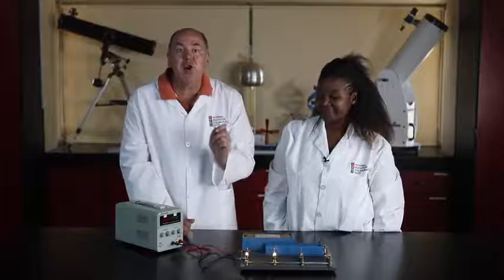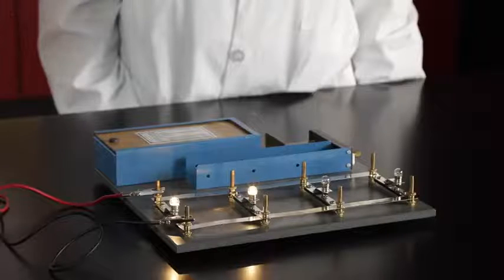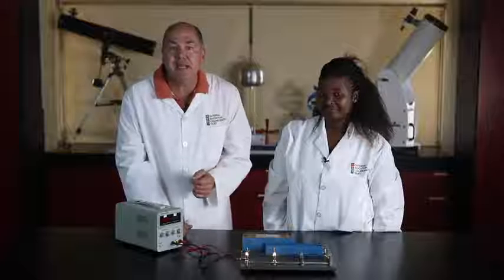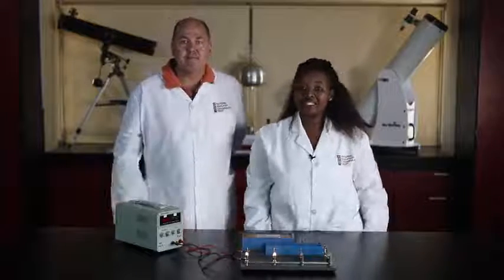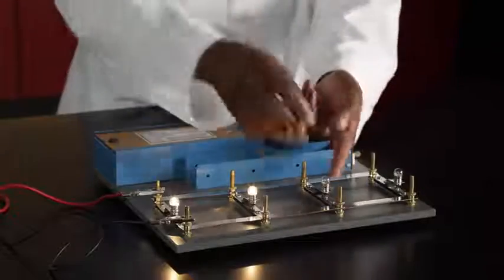Parallel circuits are current dividers. The current splits up as it passes through each branch of the parallel circuit, and it joins up again to pass through the power pack. So adding more and more identical light bulbs in parallel simply increases the current in the power pack. All the light bulbs shine equally bright.